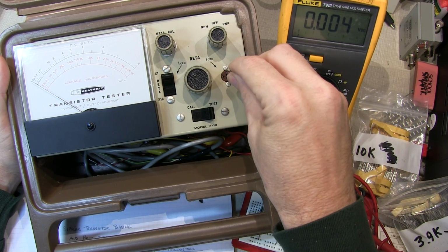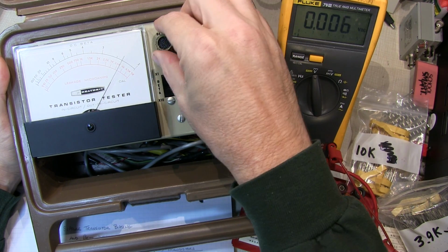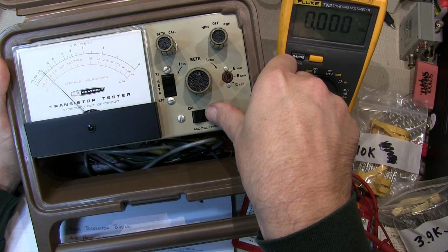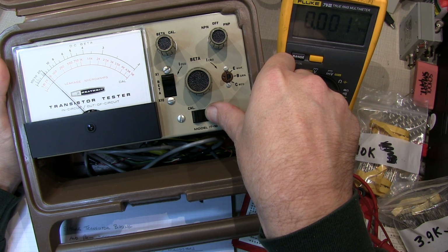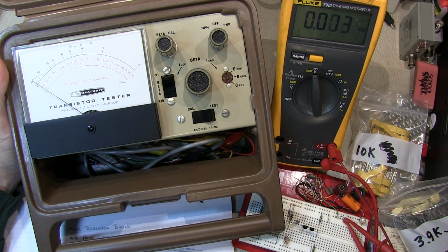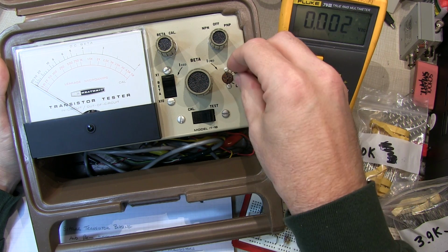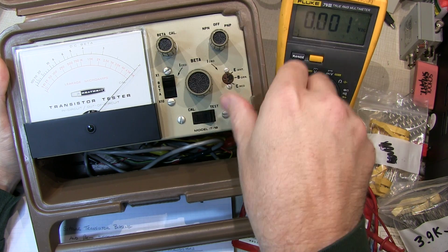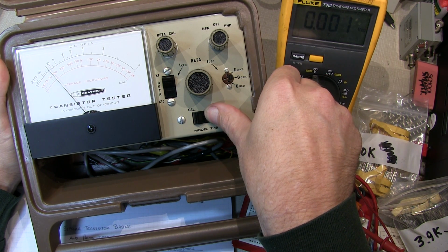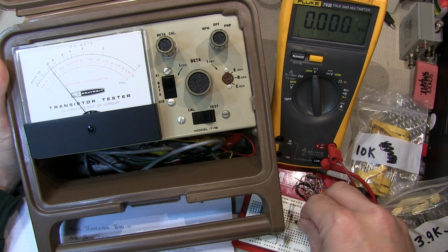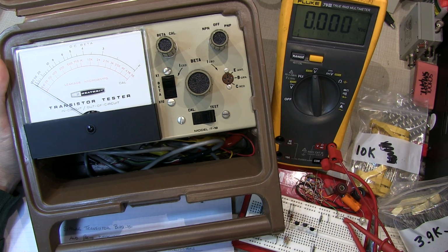Okay, so let's measure the beta of each of our 3 test transistors here. Adjust the calibration on the meter here. And this nominal, first one we'll call nominal, is just shy of 180. We'll just call it 180. So record that value here. The next transistor, same type, but just from a different lot. Let's adjust the calibration on this one here. And beta, this one looks like about 115. So we'll record that as 115.